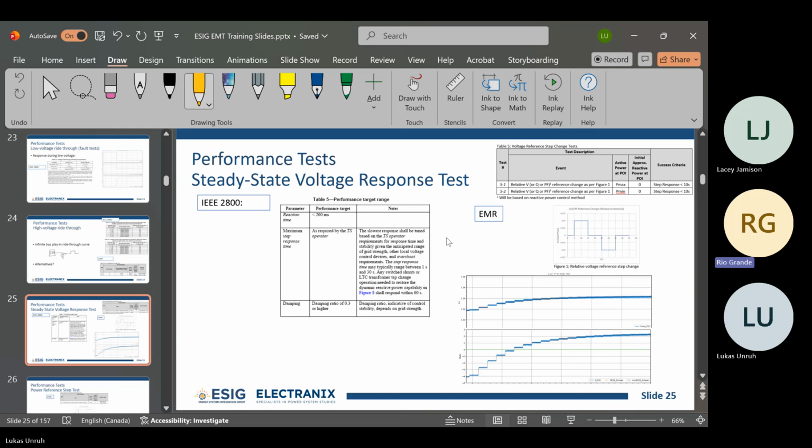There's quite a bit of delays involved in these closed loop plant level voltage response tests. You have to measure that there's a voltage change, and you have to process that through the plant controller, and then spit out a new command to the inverter. There might be some Modbus communication between the inverter and the plant controller, which will slow things down as well. So that round trip can be significantly longer than 200 milliseconds. So maybe it'll get revisited, but it's pretty hard to meet this one, I would say.